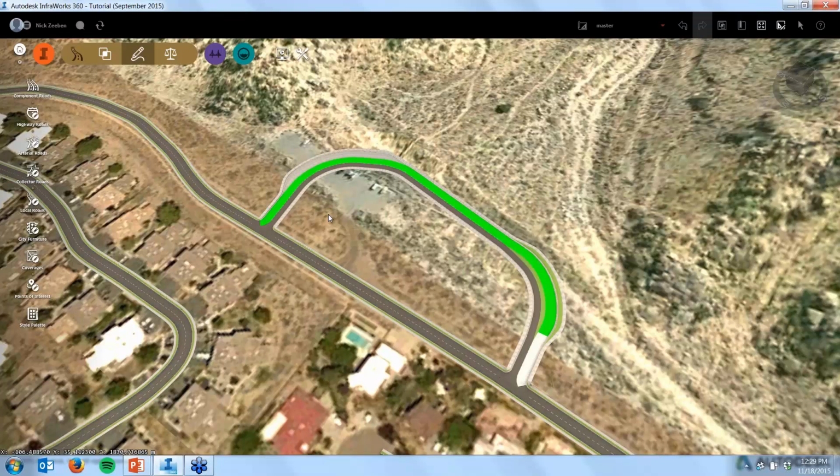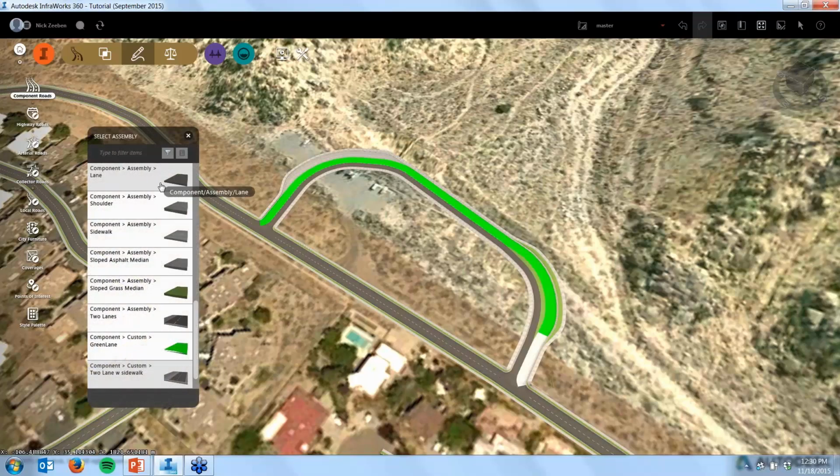Yeah, so as I showed you, within the realm of what's available today, you can create or modify any of those existing components. So you need to start with one of the predefined ones. So it's a lane, a shoulder, a sidewalk, or one of the curbs, and then you can manipulate those values like I showed earlier, right? So again, if I do another example, I'll show curb just because it has more interesting values.